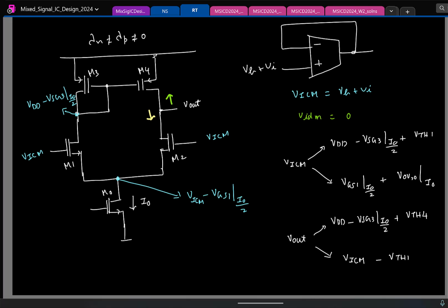No, that's what I mean. Why is VDD minus VSS a problem? I mean, we have made sure that the supply of VDD and 0, this is the maximum you can go for the input common mode range so that things are in saturation, right? Oh yeah, that is another condition, but that's like saying it can be between minus infinity and plus infinity, right? What you told is correct, but a stricter condition is what we are looking for. So one he suggested is correct.